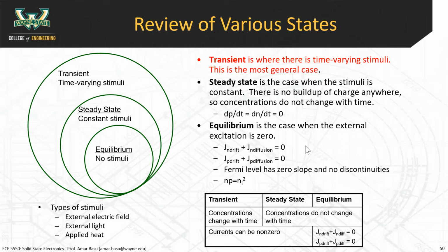Now, does anyone know how fast fiber optics works? Speed of light. How fast do these LEDs have to blink? Typical fiber optics works at gigabits per second. That means this light is blinking at 10 to the 9th hertz, and the receiver has to be working that fast too.